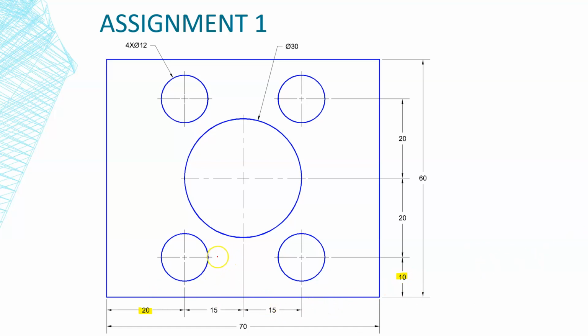So this line here connects here, and these connect all the way up here at the top. If you remember that, then that's going to make your job a lot easier anytime you're encountering something like this, because typically on drawings, some drafters or designers will put these lines on there and some of them won't. But you can assume that if it's not dimensioned by something else, that it is in line with it.